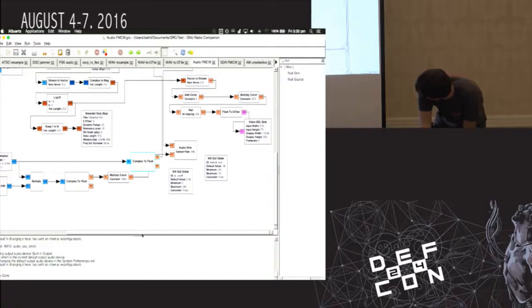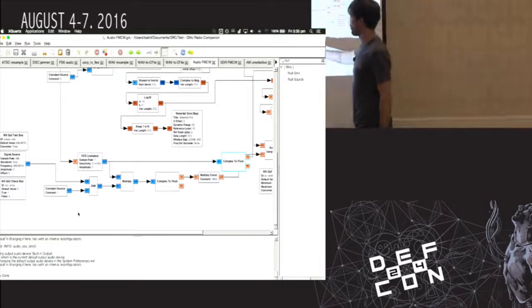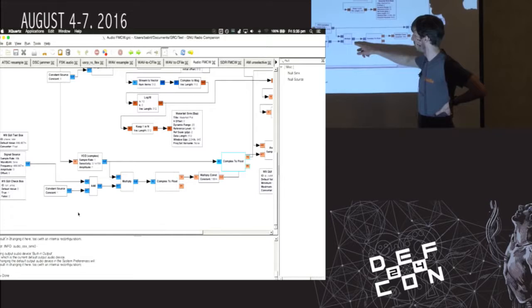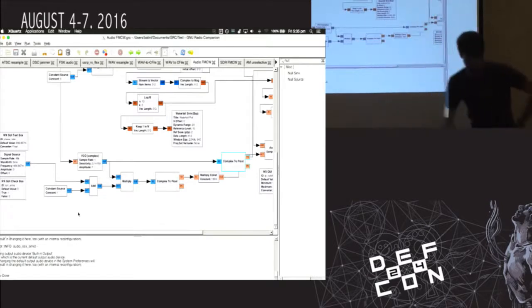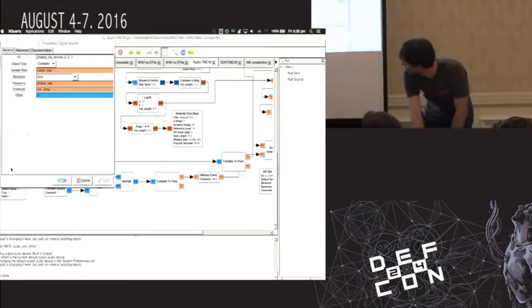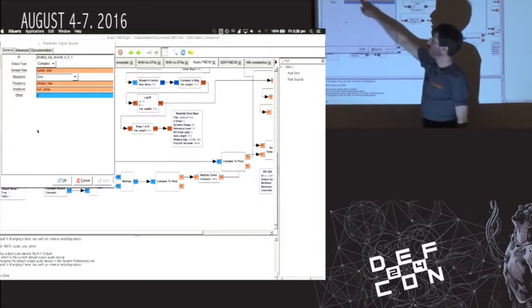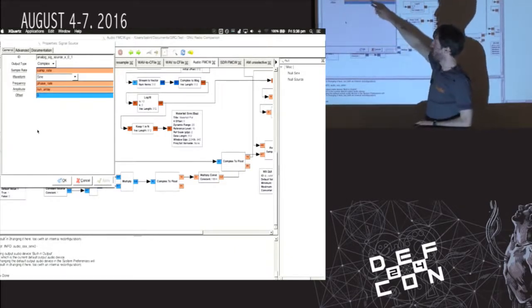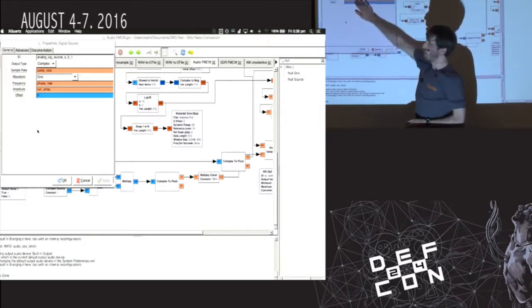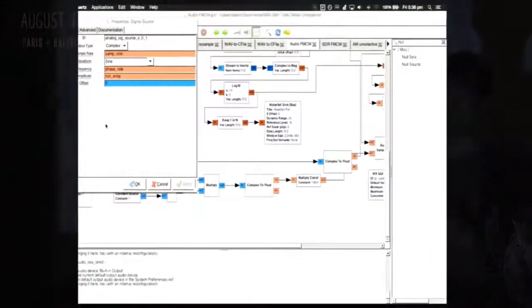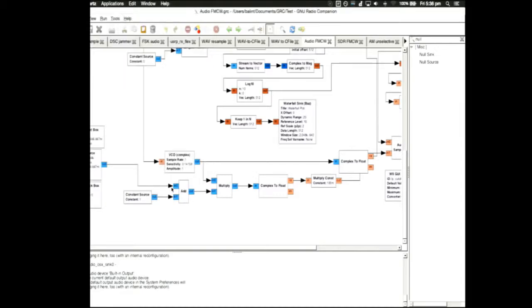and then with the array, we essentially have, that's what I forgot. So in here, in the signal source, the amplitude is actually set to run array. So if run array is on, we're actually going to get samples coming out of this with all sorts of ranges of values. But if the array is not running, then amplitude is 0. So this is going to be producing samples, but they're all going to be 0, which is as if it was turned off. So if the array is off, this is producing 0 samples.